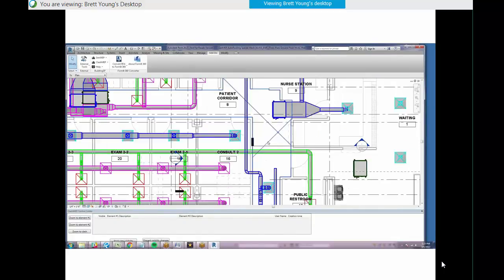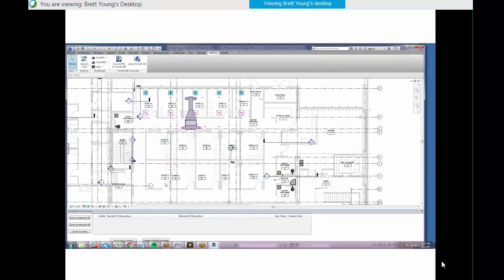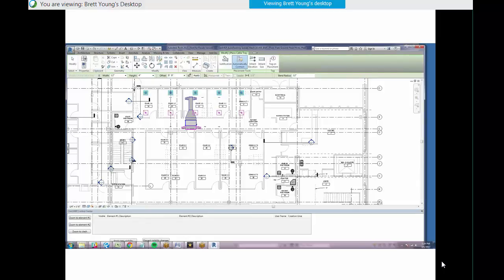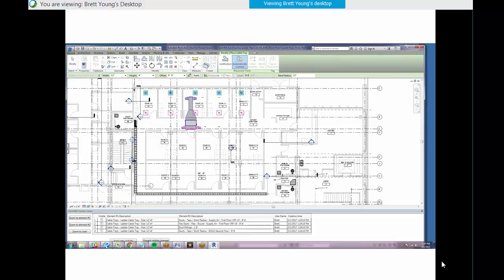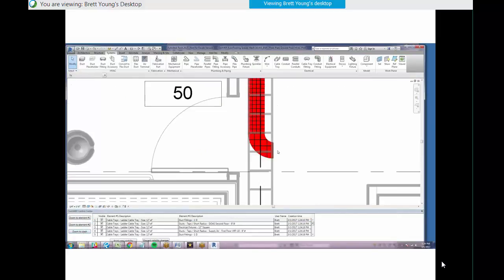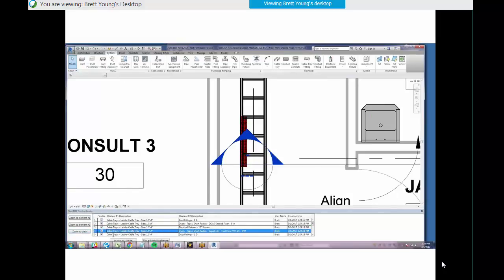So here you have Revit, and ClassroomMP does real-time clash detection within Revit. Here we're unlinking or hiding the mechanical system, and then we're drawing in a cable tray and looking at the clashes, and then dynamically declashing it as you go, right? There's your cable tray, and you can see below in the table there's a list of all the clashes that cable tray hit, and we're graphically showing it on top of the plan within Revit.